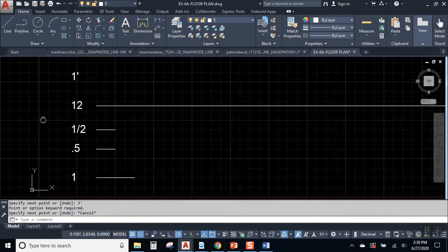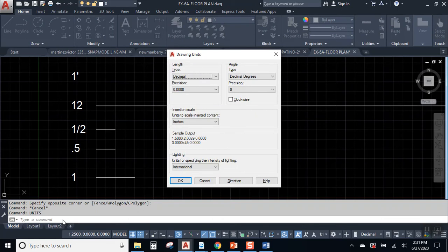If we're working with drawings and we're drawing large things, you know, a parking lot, a house, an apartment building, a refinery plant, we don't want to have to convert every single measurement into inches, right? If something's 27 feet, do you really want to figure out how many inches that is? That's ridiculous. So we can ask AutoCAD to work in feet. We just got to know how to ask it. And the way we do that is we work with our units. So down on the command line, I'm going to type in units, U-N-I-T-S, and it will open up the dialog box for units.